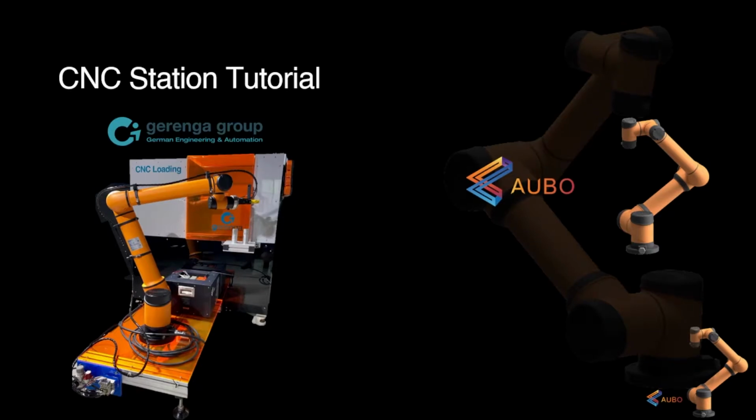So we have a workpiece holder with two workpieces here. We have the gripper. Inside the CNC station, we have a simulated chuck. So it's a 3-jaw chuck here, pneumatically actuated. You can see here in the control box, which is open on top, we have the digital outputs set. So we don't get a signal back if, for example, the gripper is closed or open. This is a very easy setup for educational purposes only, right?